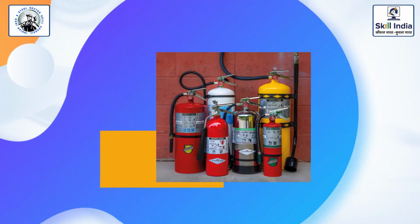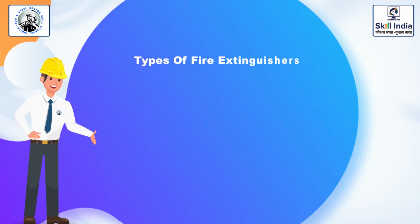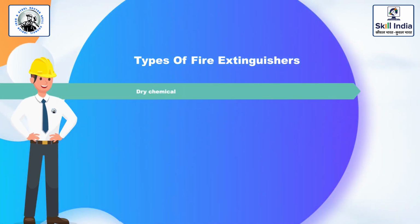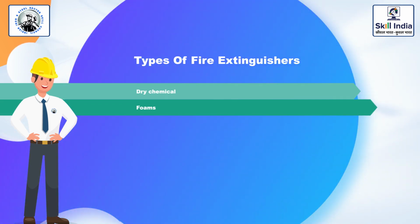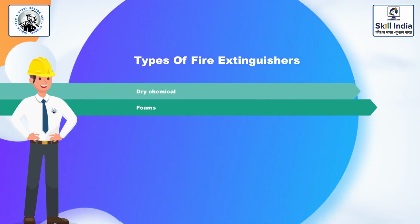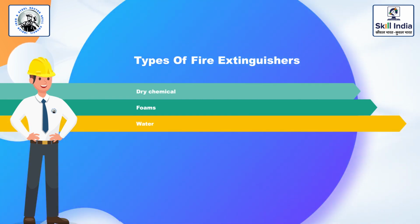Let us understand the types of fire extinguishers. Dry chemical. These fire extinguishers are in powder form and they stop the fire production through free radicals. Foams. Foam fire extinguishers are applied over aspirated or unaspirated fuels. The foam released from the fire extinguisher forms a blanket over the fuel and cuts the supply of oxygen to the fuel.